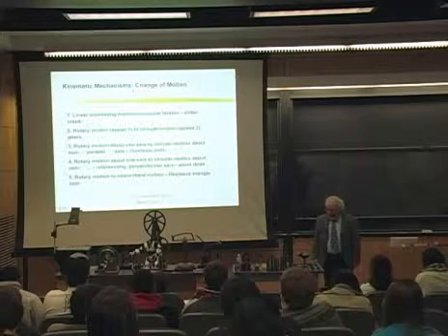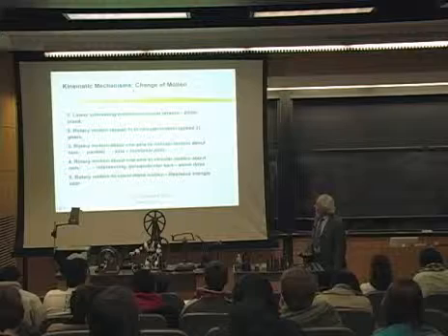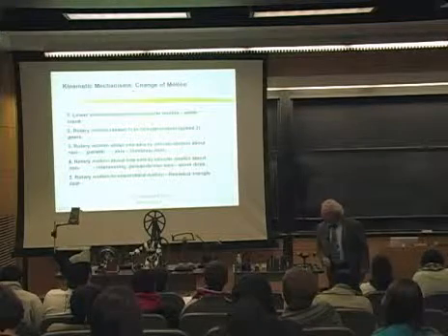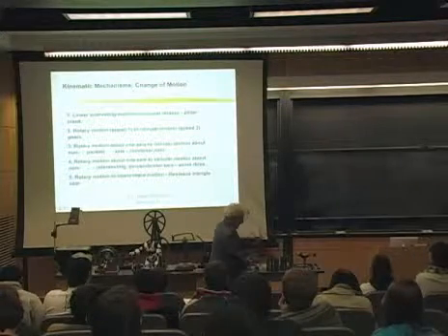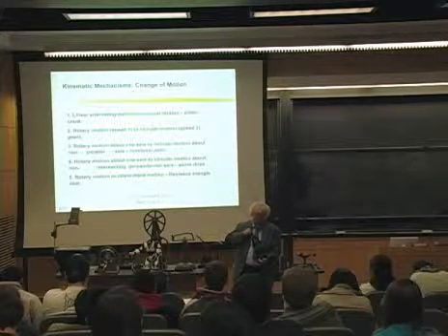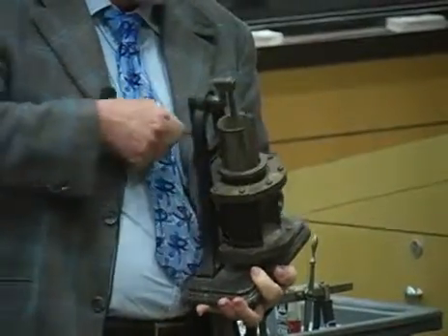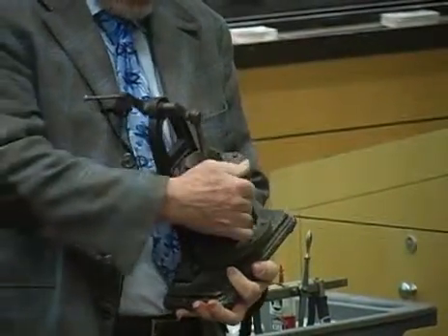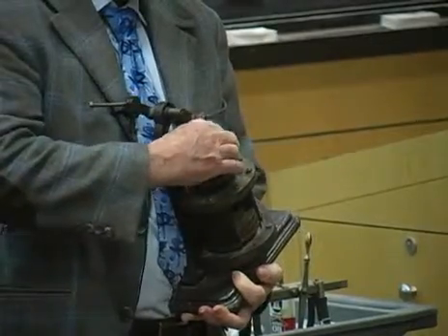So, for example, if we talk about the slider crank mechanism here, we can either think of this as converting rotary motion into linear motion, or, of course, in the real engine, the engine is producing the linear motion, and the linear motion turns it into rotary motion, which eventually ends up to rotary motion of your wheels, which eventually ends up to linear motion in the car. So we're all about converting motion from one form to another.